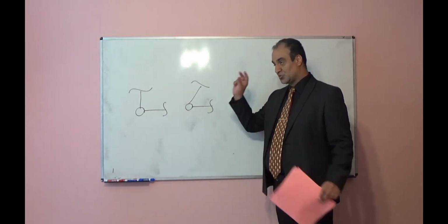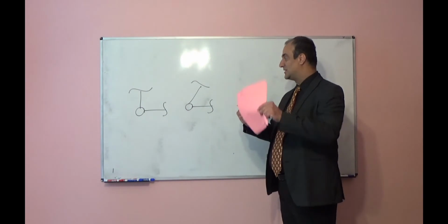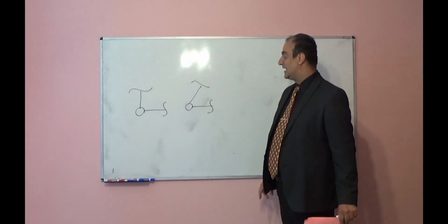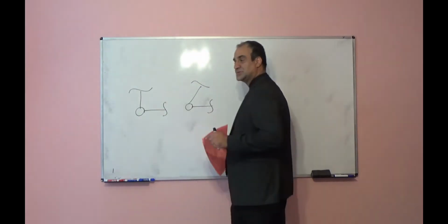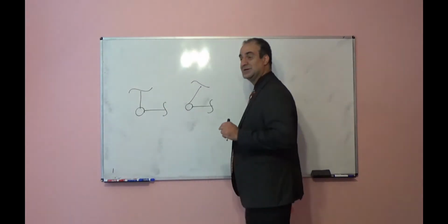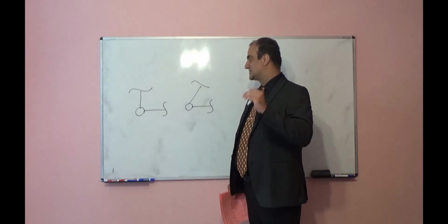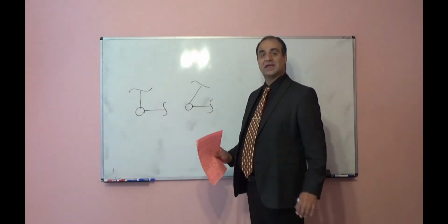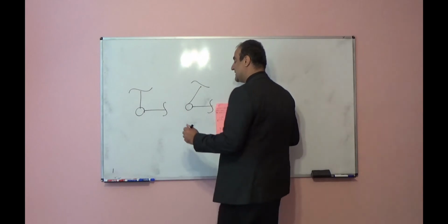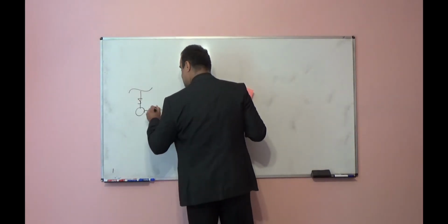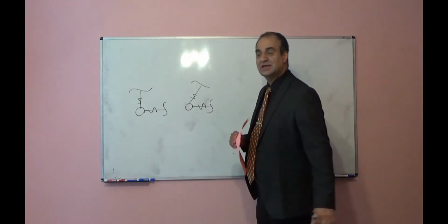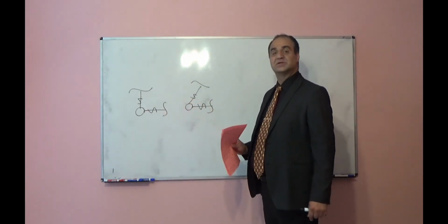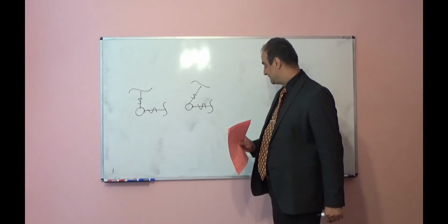So you have a joint pin, two members attached to this joint, and those two members are not collinear members. You see, they are not in the same direction, and there is no external load at the joint or any support. In that case, both these members become zero force members. Internal force in those members is equal to 0.